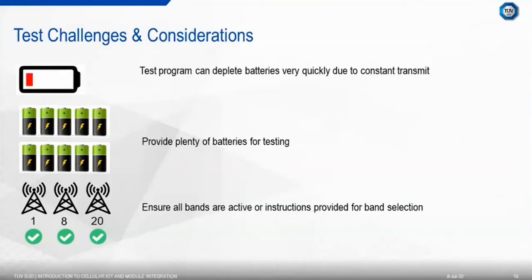We've seen some samples which have complex gasket arrangements that may impact the spurious emissions results if not correctly fitted or damaged in reassembly. We've seen some products which have required special tools to dismantle the device. Other cases have included batteries which are soldered to boards, which can be problematic if access is difficult. We've seen some cases where a customer has needed to provide 10 test samples to cover the test time required for RF and EMC testing, as the battery was not able to be replaced.